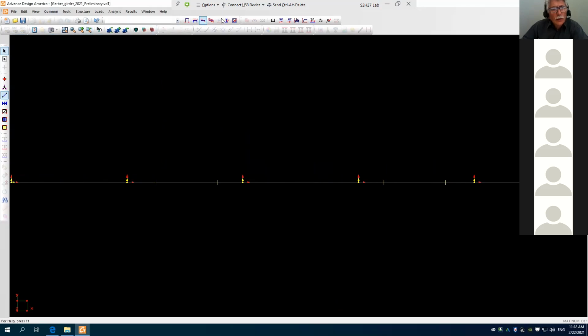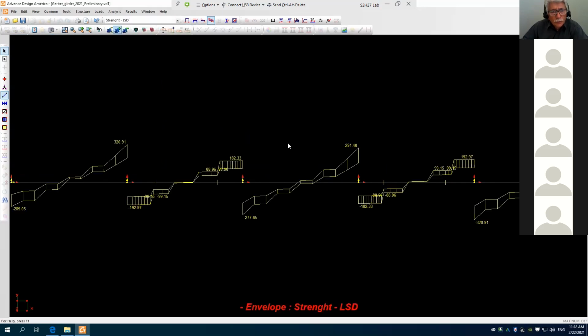Now, in theory, if I go to my strength. Exactly, 180. Yeah, but then down here is 277. Yeah. It's the same shear. Do you understand? All it did is that it reversed it, but it's the same shear value. Okay, now I understand what you're saying. No, what we did is that we changed it, in other words, it was 277 up here, and I now believe the 277 was there before. Exactly. All you did is that you reversed the shear.